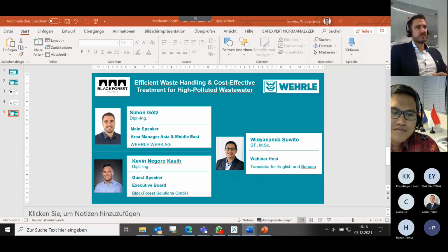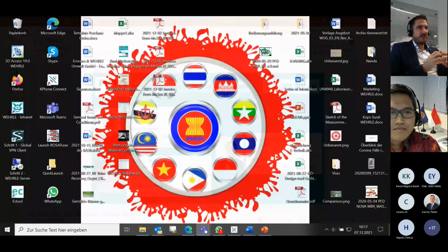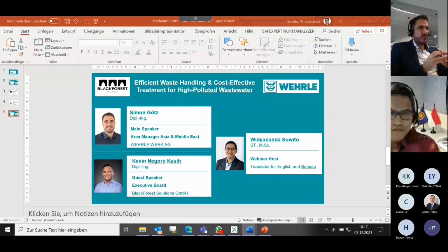It will increase the OPEX drastically if you need your own machine for producing pure oxygen. The reason is that with our aeration ejector system, we can use just normal air. For sure, the oxygen content in normal air is much lower than in pure oxygen, but through our ejector system and the really high water table, we have a really good alpha factor. Alpha factor means how well the oxygen can go into the microorganisms. This high alpha factor helps us run the plant with normal air